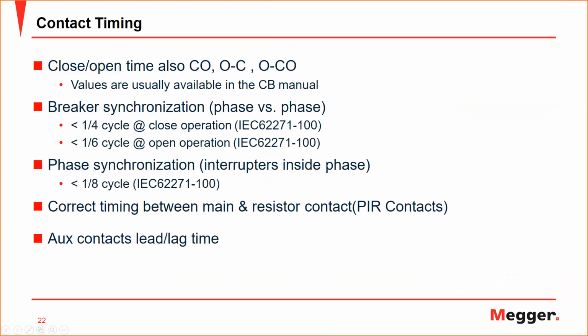Okay. So when I talk about contact timing or timing test, basically, it is the time required for the breaker to complete, from the first pulse giving to the breaker open or close until the breaker contacts first separation or first touch, depending on the operation. So the sequence of these tests usually will have, I would say, close test, where you test the breaker how much time it takes to close.